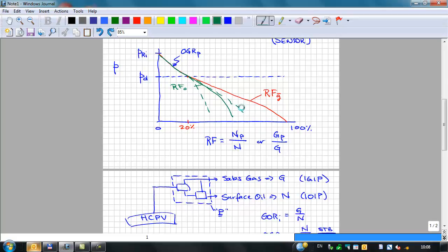No, you never pick up, you won't pick up at low pressures a lot of this retrograde condensate. Now, the thermodynamics say that if you bring the reservoir to 1 bar, all the K values of these heavy components are marching their way to very high values. Theoretically, you can vaporize the oil, right? From the K values getting higher and higher.